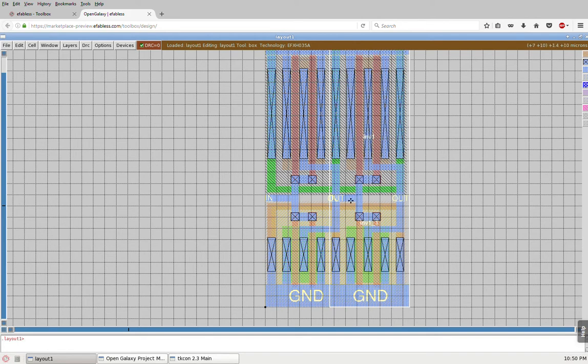And now if I go back again on the out node of the very first one into the in node of the second one, you can see exactly how things connect, and you can see that the drains of the first inverter connect to the gates of the second inverter. And then again, I can repeat this over here, using S repetitively, and you can see the output gate. So it's very easy to trace signals in Magic. It's one of the advantages. I can actually do that also on the ground side. Let me do this on the ground nodes over here.